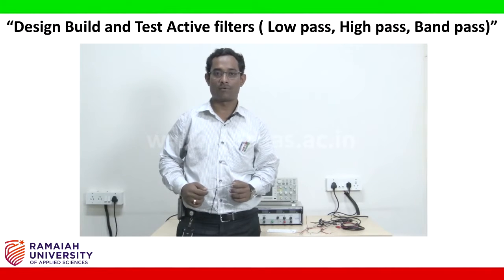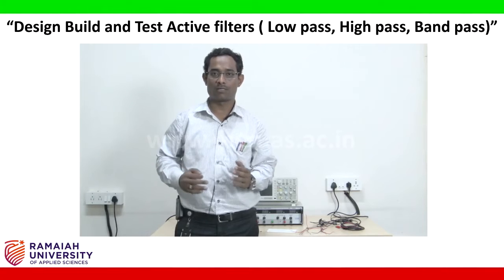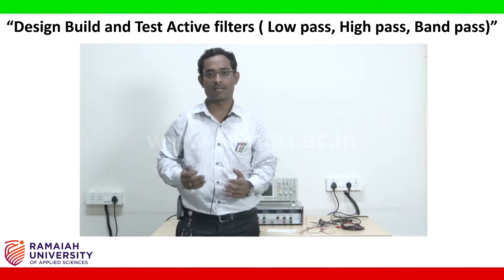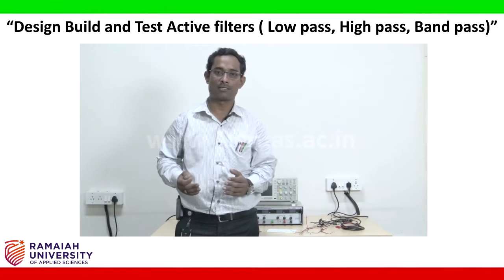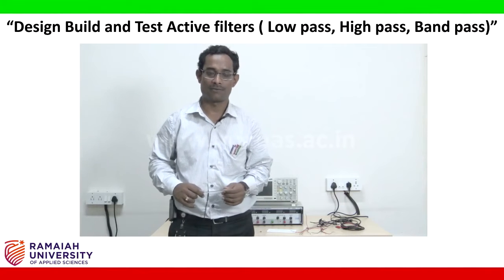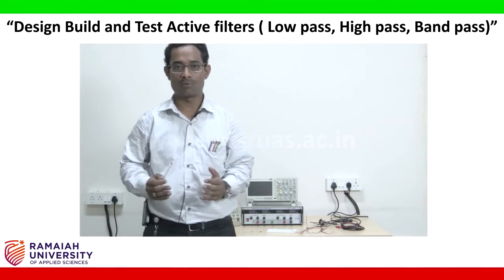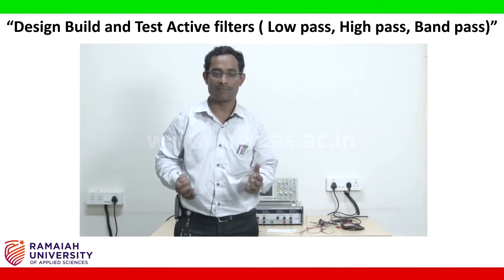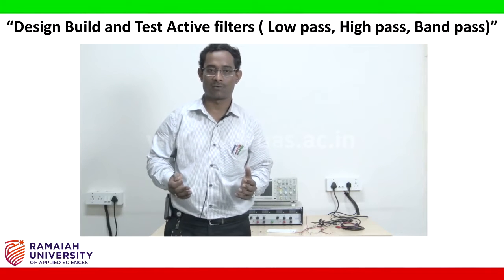So we already know what is low pass filter and how we are going to design. Both are slightly similar. Instead of placing a resistor, we need to place the capacitor values. Instead of placing the capacitor, we need to place the resistor values. Only small changes will happen between the high pass filter and low pass filter circuit connection.